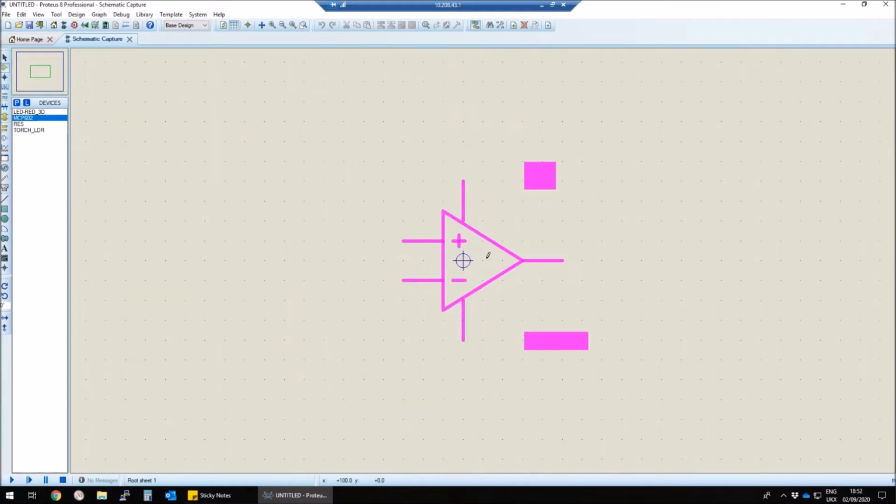An op-amp has 5 pins: the positive and negative supply pins, an output pin, and 2 input pins. The plus pin is the non-inverting input, and the minus pin is the inverting input. They are named such because if the op-amp is operating as an amplifier, then injecting an input signal into the non-inverting input will produce an output in phase with that signal, while injecting a signal into the inverting input will produce an output which is inverse to the input signal.